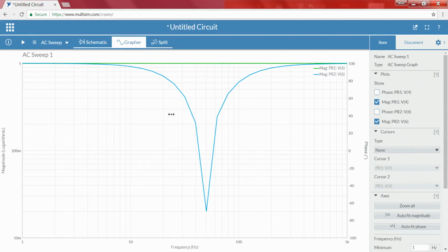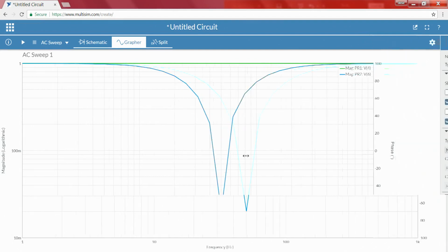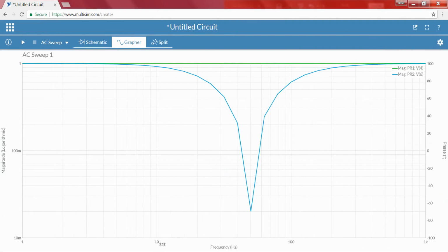Now, if we clearly see, this is in the frequency domain. So, if you recall how we measure in a frequency domain, in a log scale it is basically 10, 20, 30, 40 and 50, right, 60, 70, 80, 90, 100. Now, we need to know the 3 dB line, this point, right. The frequency at this particular amplitude is generally the cutoff frequency.